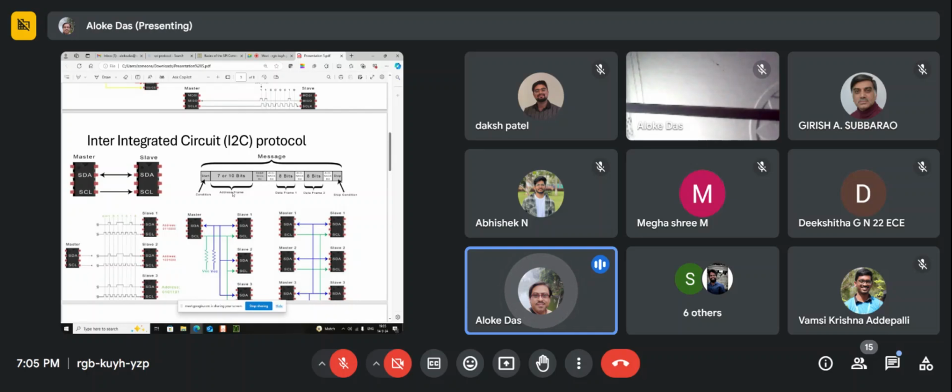The data will come as 0 and 1, like that. In one line, it can only be up and down of that signal, nothing more. But this thing you have to implement in your design, in your Verilog code. You have to take the first 7 or 10 bits, and make sure you use only 7-bit or 8-bit. After the first bit, if you see this is 0, then you say, okay, now transmission is happening.